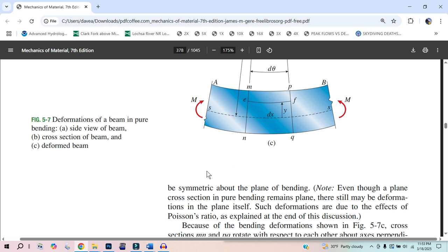If I throw in a value of 0.002 on this side of strain, which says my thing changed in length to 1,002 millimeters, and it was 1,000 millimeters, that's a change in length of 2 millimeters divided by the original length of 1,000. That's going to give me 0.002. So when I plug in that number, how do I pop out this 50,000 or 58,000 pounds per square inch?